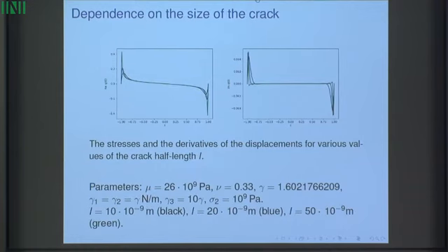Now, again, for the crack, this is the dependence on length scale. So again, half length equal to 10 nanometers, 20 nanometers, 15 nanometers. And again, you can see that the smoothest solution is actually the one with the smallest length of crack. Remember that our problem parameters inversely depend on the length of a crack, so correspondingly the smaller the length of a crack, the larger the influence of this surface energy, the smoother your solution appears to be near the crack tips.